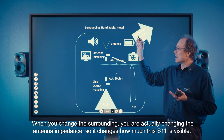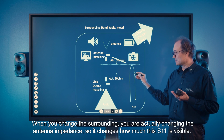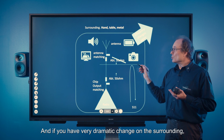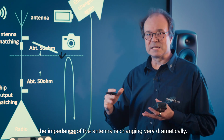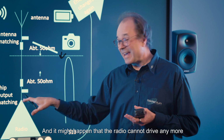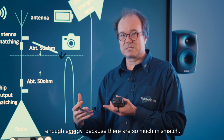When you change the surrounding, you're actually changing the antenna impedance, so it changes how much of this S11 is visible. If you have a very dramatic change in the surrounding, the impedance of the antenna changes very dramatically, and it might happen that the radio cannot drive enough energy anymore because there is so much mismatch.